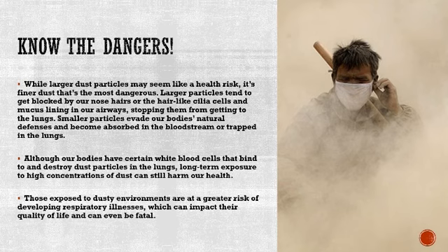As plumbers, you are working in an industry where you are constantly exposed to this danger, especially if you are doing one of those four things, which is chasing of walls, digging of trenches, if you are doing any type of drilling for anchorage, as well as types of core drilling as well.